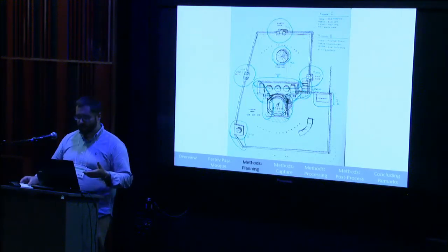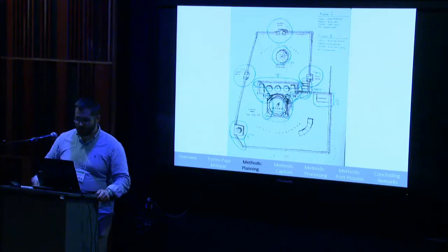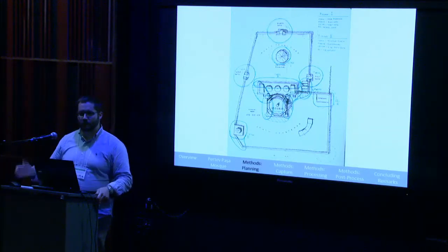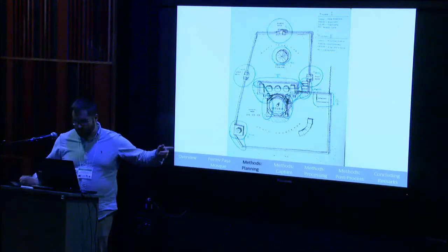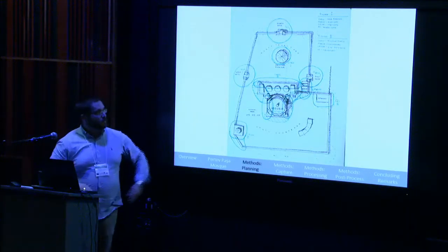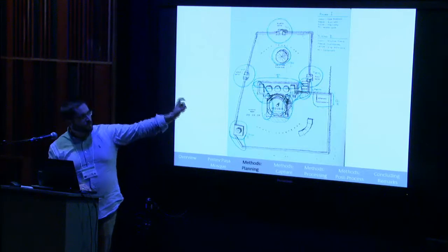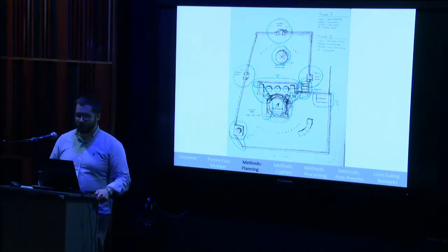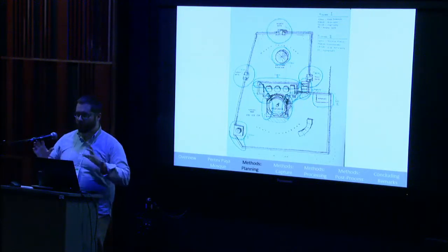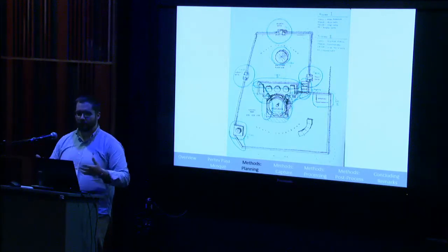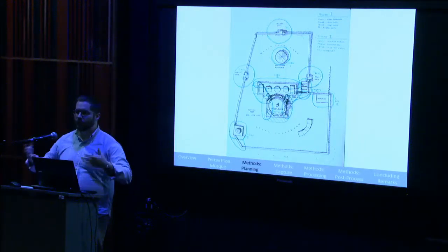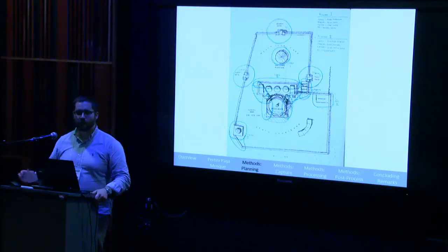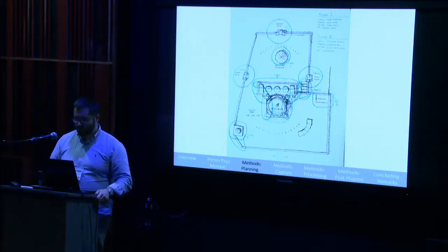And then, of course, depending on the size and complexity of the project, you can repeat those steps as many times as you'd like. As indicated here, we planned to break down the porch and the sides and the outside of the mosque into separate campaigns, just due to the limit of photographs you can submit at once. And then the idea would have been to combine all of those completed photogrammetry models into one supermodel, something very similar to the laser scanning method, where you do multiple scans and then combine them later.